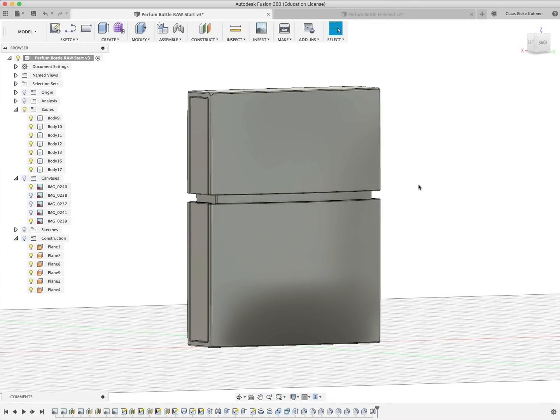Okay, so that kind of sums up the way I modified or created everything in the parametric workflow. I hope you saw some of the advantages of the parametric features, but also that you need to be very particular about how and when and where you do these things. Now this demo is really fast because I memorized how to build this one. I also built this one in class, but if you're new to it or you explore it, you might not really know all the structure yet, which is actually the downside of parametric modeling. If you don't really follow a clean structure, you can later have a really difficult mess inside your design tree, and then you might have to restart and rebuild it in a cleaner way.